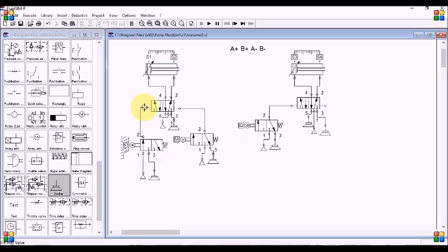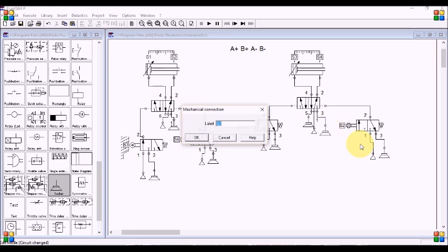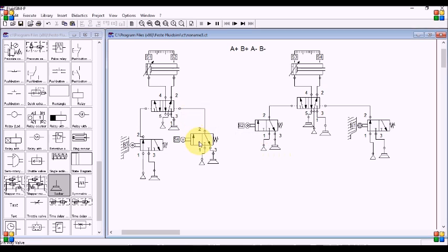Right, now what has happened? A plus, B plus, A minus happened. Once A minus is done, I have to go for B minus. So S1 is true. If S1 is true, then only I have to go for B minus. So I'll attach this over here, and again a set of compressor and a sucker over here. A plus, A minus. It should be S1, right?